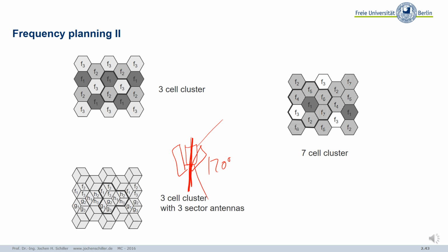And in Germany, we have about 60,000 of these base stations, 60,000 of these antennas. We have way more, but these are the big base stations. We have way more for replicating the signals. For example, if you go in the underground, we have special antennas there so that you can use your mobile phone in the underground, etc. But something like 60,000 of these antenna sites we have. And there it's quite complicated to do the frequency planning, to avoid interference, to borrow channels, to do all this, to be also a little bit dynamic.